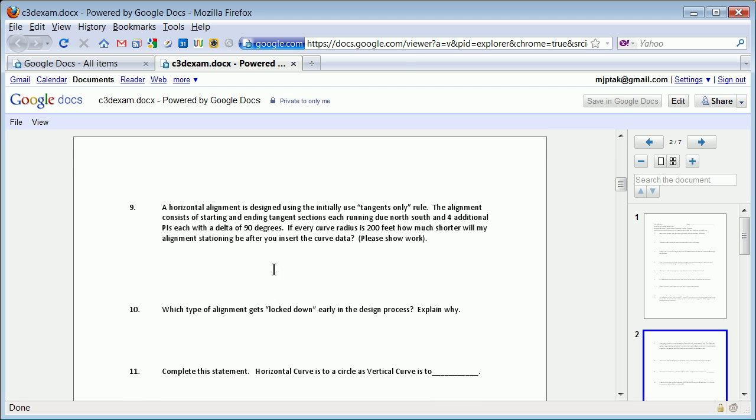If you go around a curve, you remember that the tangent distance is equal to R times the tangent of delta divided by 2, which means that if you go around 4 curves, you essentially have a square that is 8R, R as a length if it was straight, and 2 pi R. And so this turns out to be (8 minus 2 pi) times 200 feet, since you are effectively going around in a full circle.